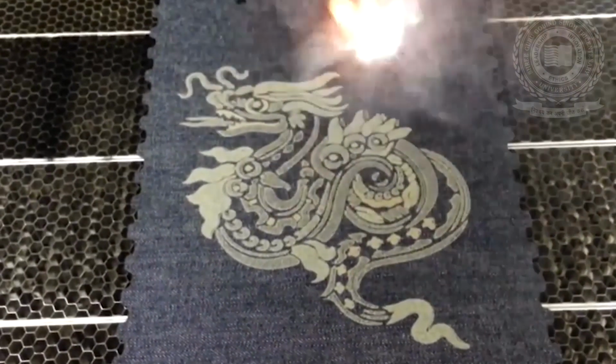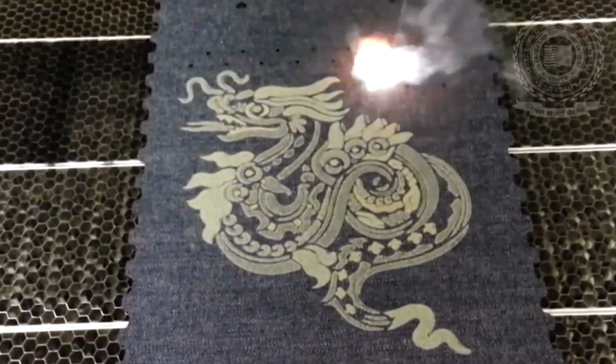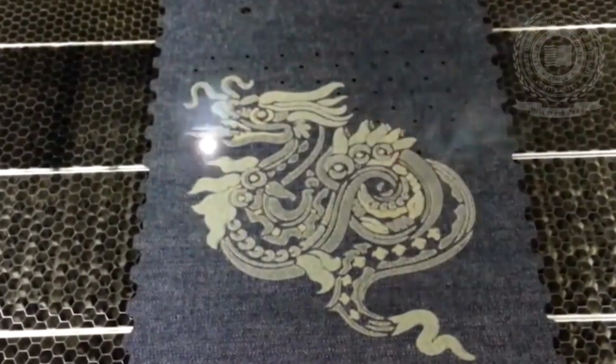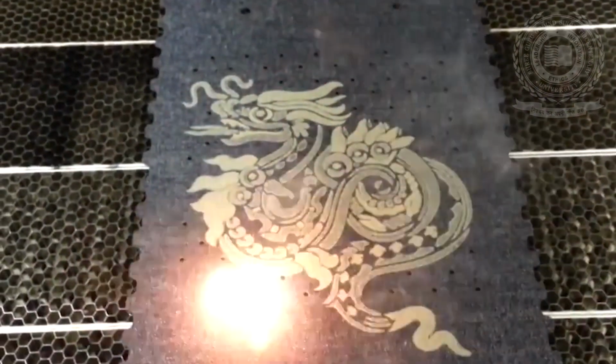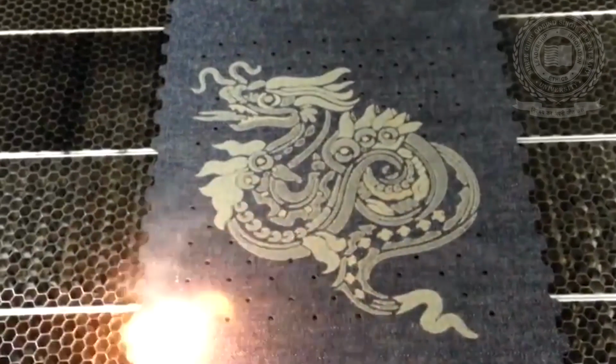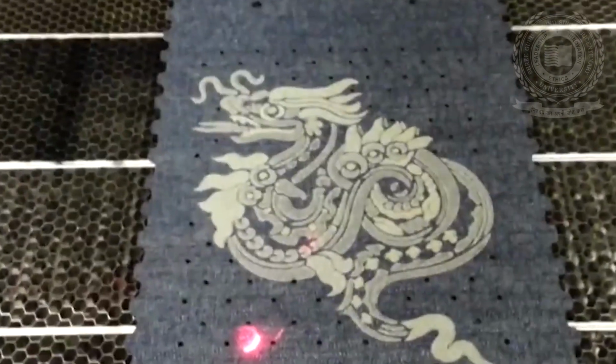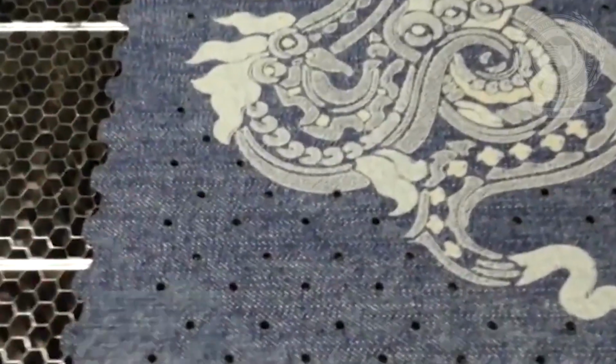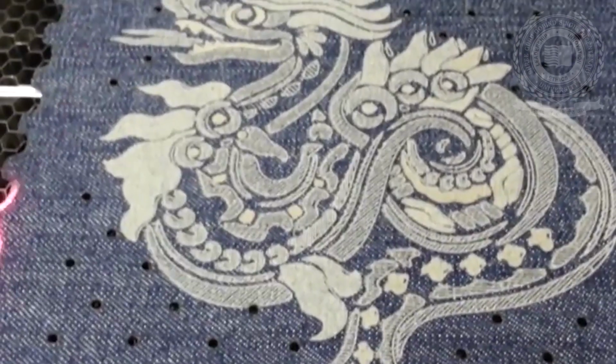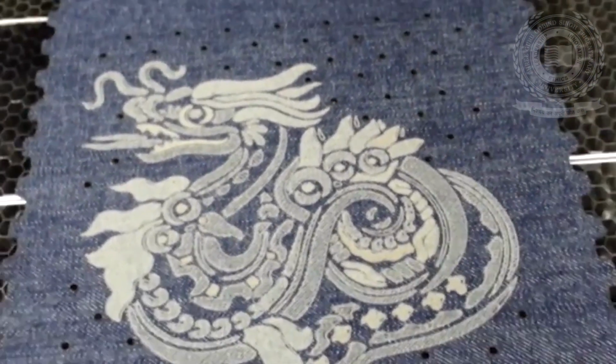It is a subset process of laser marking where the object is actually marked beneath the surface and is the most common of all the laser marking applications. The depth of the engraving made will depend on the dwell time as well as the type of material being used.